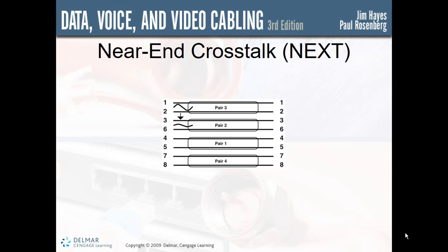Poor quality components, including patch cords, termination blocks, plugs, jacks, or cables, will cause failures also, especially at high frequencies. As mentioned earlier, split pairs will cause unbalanced transmission and high crosstalk. It is with near-end crosstalk testing that you will most likely find those problems.